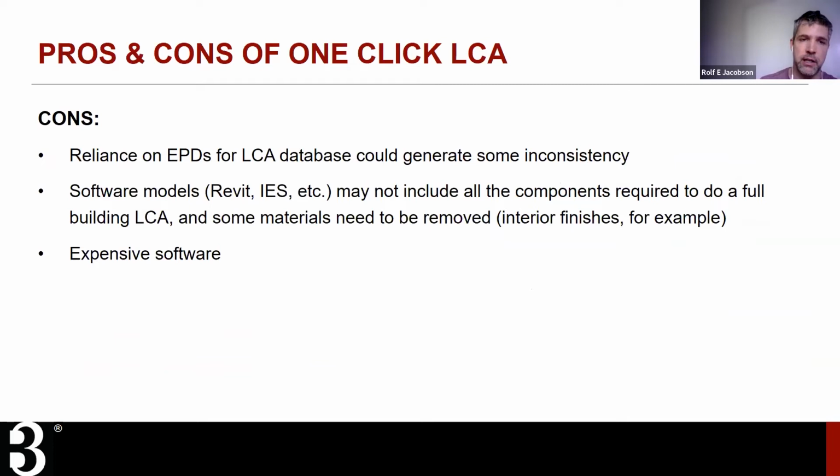Okay, on the con side, EPDs are sometimes a bit dangerous to use for an LCA database because EPDs are coming from a wide variety of different manufacturers, and some of them may be using different scopes for their products and materials. And so the consistency can suffer a little bit on databases that are built from those.